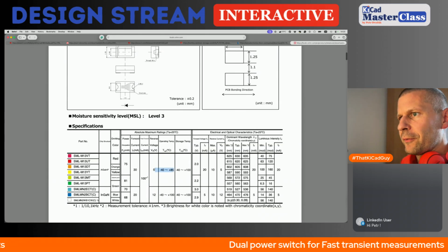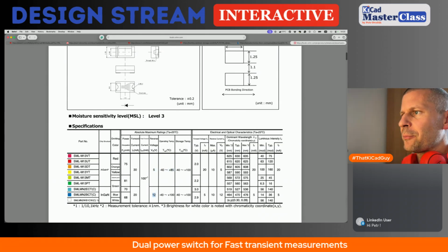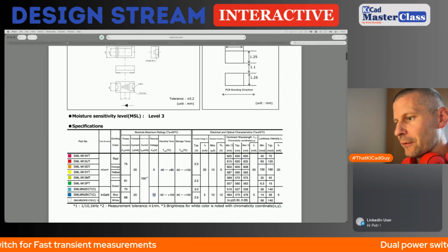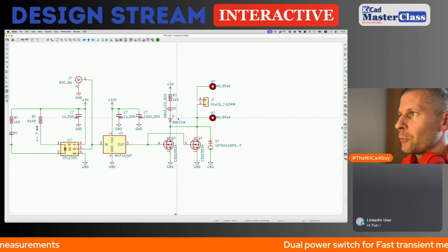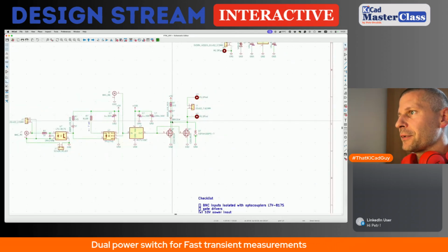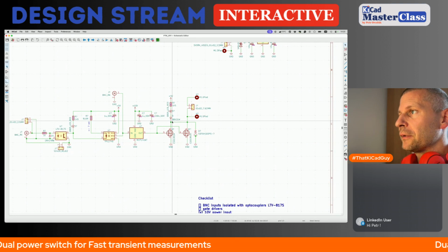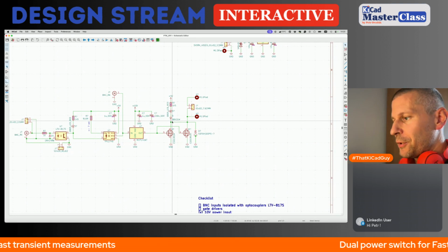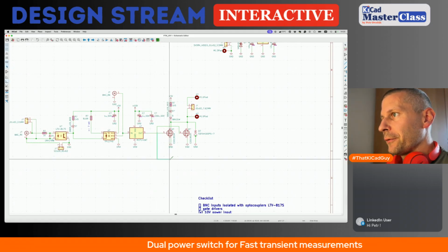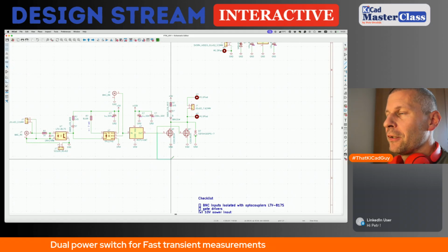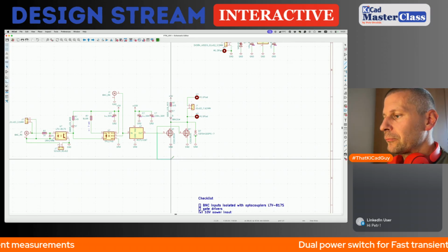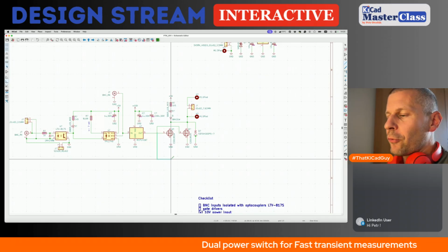Reverse voltage is 5 volt. You can see at least at max 12 volts for blue ones. So we need to place the protection diode here to create some barrier against damaging this LED. Other option would be to use an auxiliary MOSFET for switching the LED.